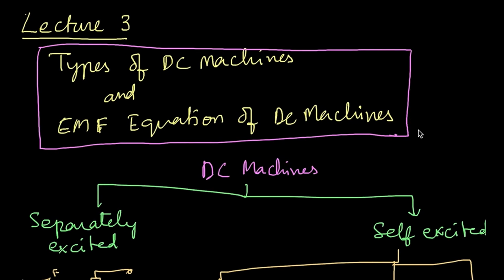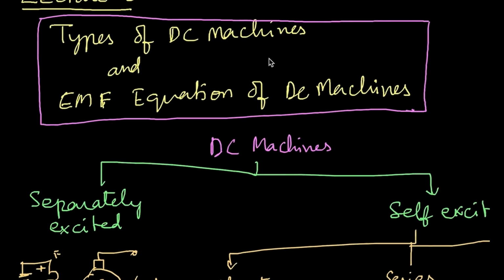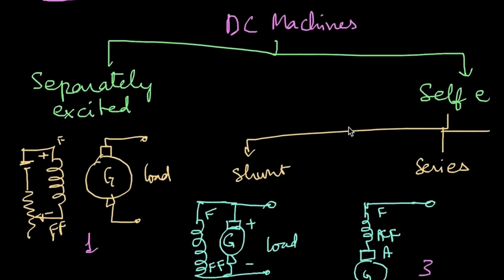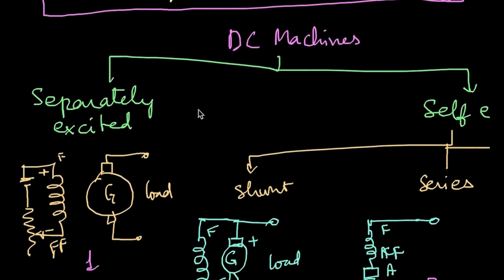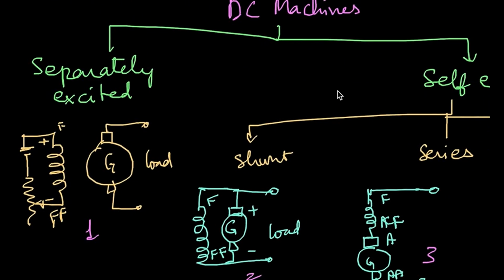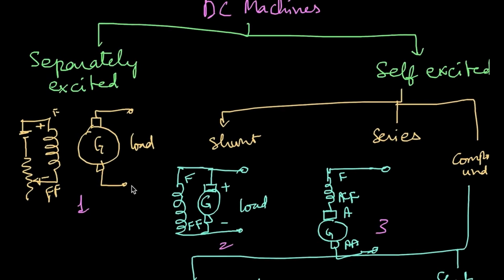So let me briefly review this lecture once again. First we begin by talking about types of DC machines, where externally how the DC armature is connected with the field and series windings is what classifies the DC machines. I talked about separately excited DC machine, where a separate magnetic field voltage source is given for the flux, and then the generator is connected directly to the load.